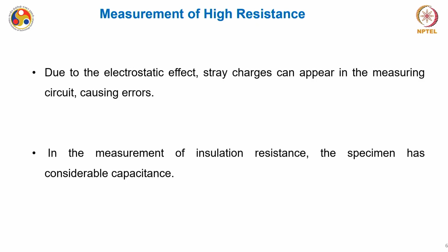In this kind of resistance, electrostatic effects have a very strong influence. Due to the electrostatic effects, stray charges can appear in the measuring circuit, which can again cause different errors. Now, in the measurement of insulating resistances, the specimen's capacitance also has to be taken into consideration.